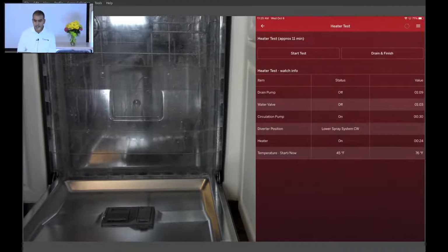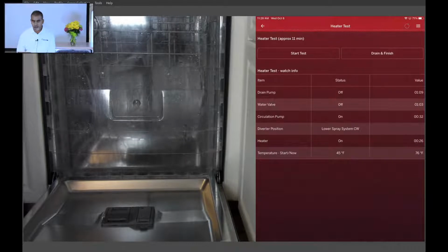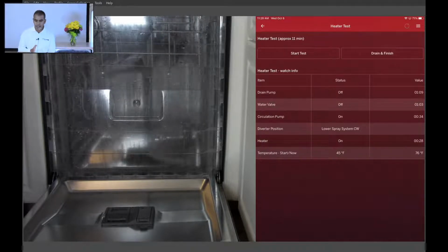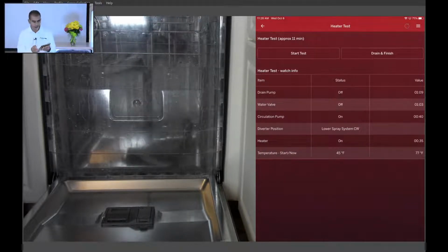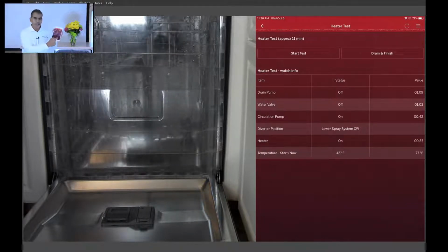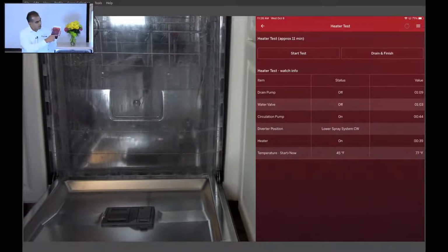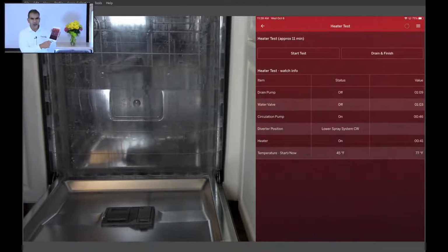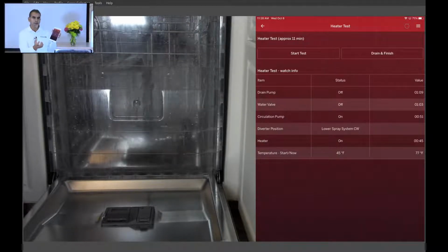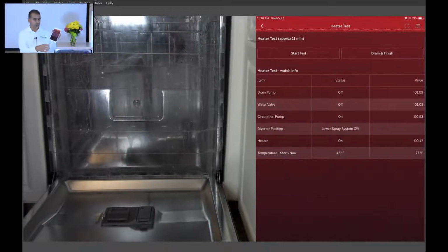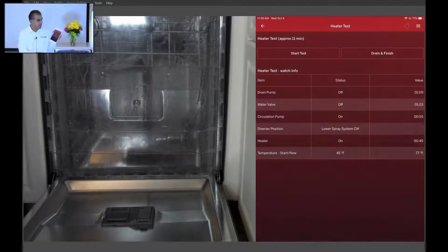Now, let's take a look at the water heater status. It is on, and let's take a look at our temperature value. Okay, now it shows that our temperature value at 30 seconds, we'll call it about 30 seconds, is somewhere at about 77 degrees Fahrenheit. Our initial value read 45 degrees, but I think that's because the water that came in was really cold. I didn't prime the water lines.